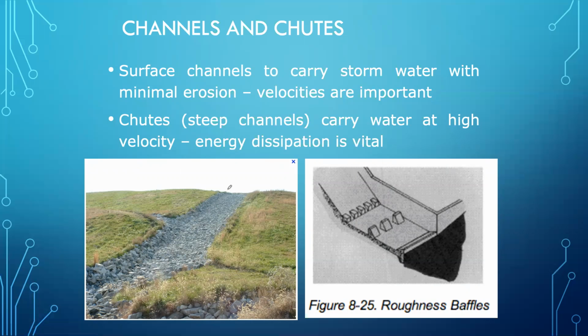And in those instances, if we have to convey water over a pretty steep topographic slope, we may not have much choice in velocity management. So instead, we have to manage the material that the channel is made out of. And I'm drawing trapezoids on what is a chute. And so the water is coming down this way.